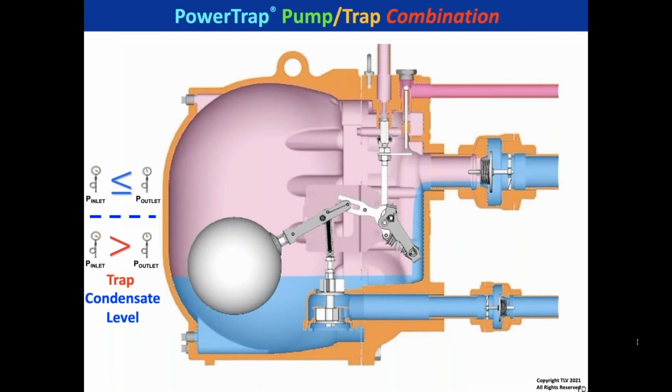But if the condensate elevates above that line, it means that you can't discharge the condensate. So it's building up inside the body. That indicates a negative pressure differential. It has to be pumped out. We're going to pump it out by bringing in a secondary pressure.